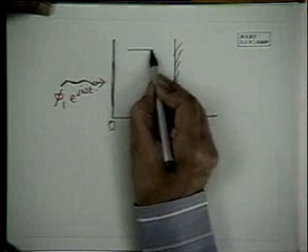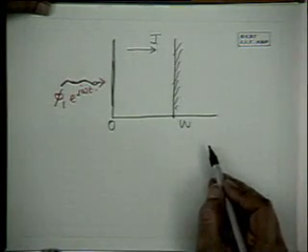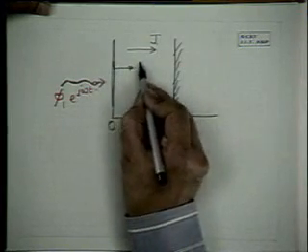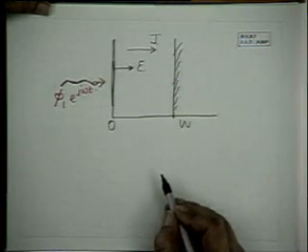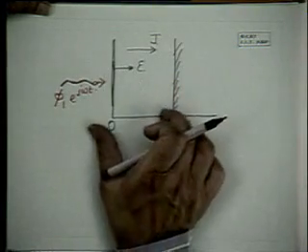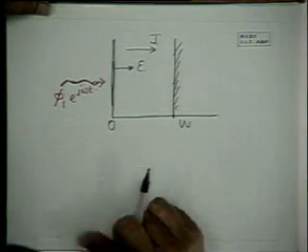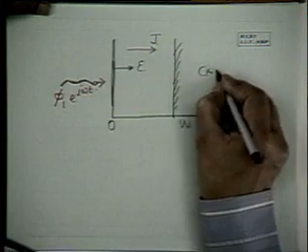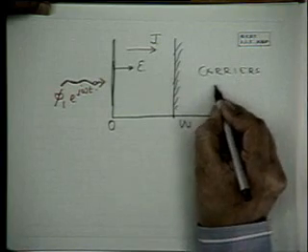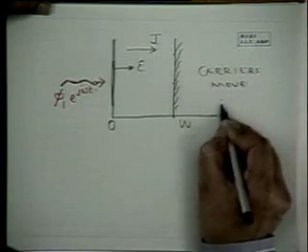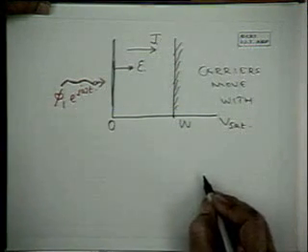Due to this we have a current due to carriers, and there is also an electric field. The electric field applied across the device is considered to be high enough to deplete the I layer. So we assume that the carriers move with saturation velocity V sat in centimeters per second.